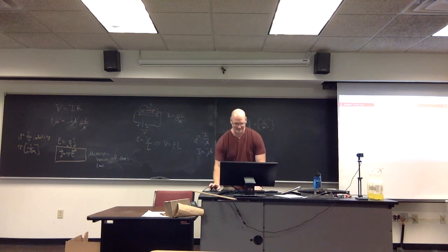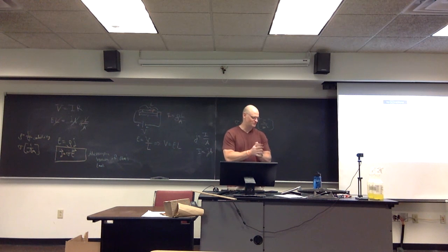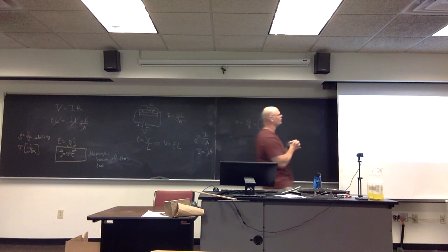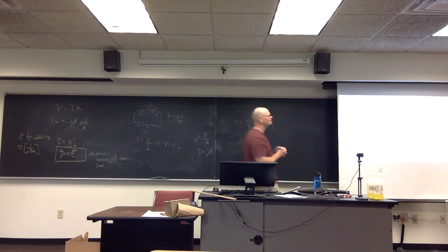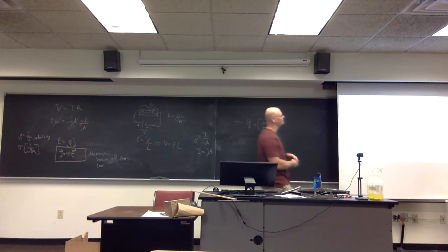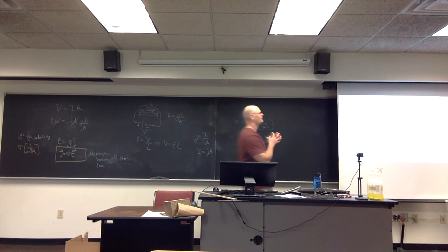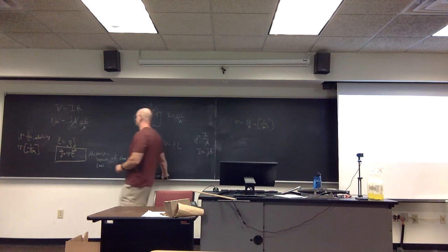So using these, let's do a couple more examples. And I did not write down the numbers for these, so hopefully somebody has calculators and can calculate the numbers for these guys. So let's do this. So this one says that we have 115 volts applied across a wire that is 10 meters long and has a 0.3 millimeter radius. The magnitude of the current density is 0.14 times 10 to the 4th amps per meter squared. And from this, it wants us to find the resistivity of the wire.